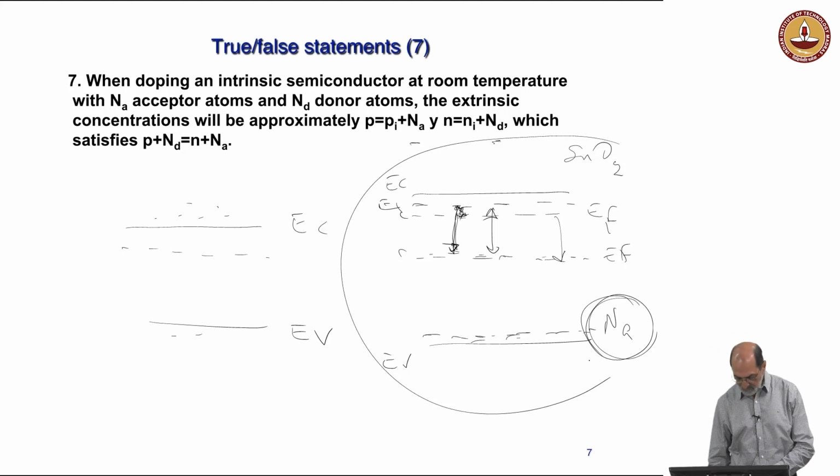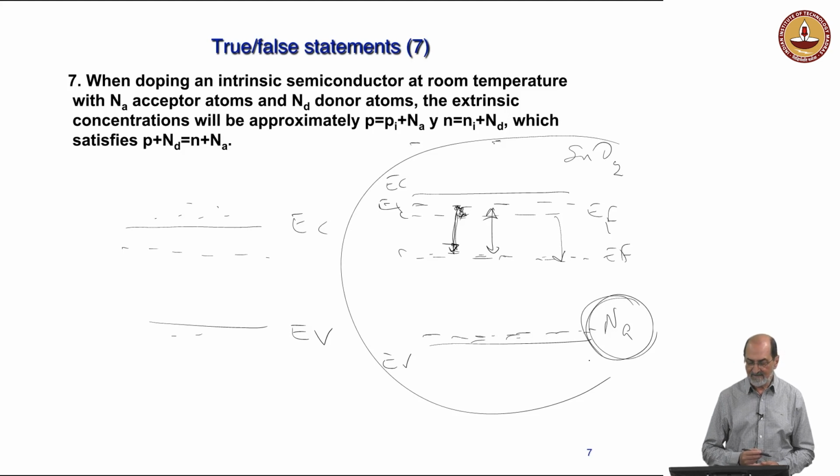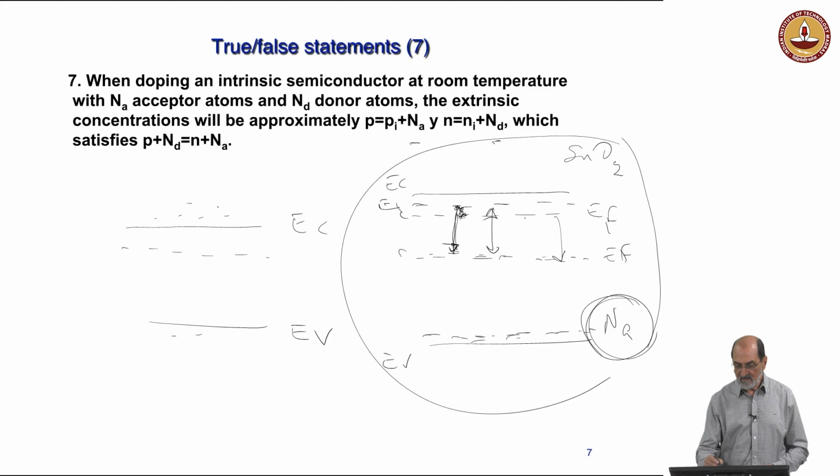What about non-oxide semiconductors, for example, gallium arsenide? In those kinds of semiconductors, we don't have the problem because the gap is much smaller, so the Fermi level does not move much, and everything is quite stable. You introduce some impurity, and everything is quite stable. So that problem does not arise there. But in ionic semiconductors, in oxides, already in the regular situation, the formation energy of an oxygen vacancy is low enough for the vacancy to form. So as long as that energy is reduced, you're going to have more defects. But in the case of gallium arsenide, it's not energetically favorable. Yeah?